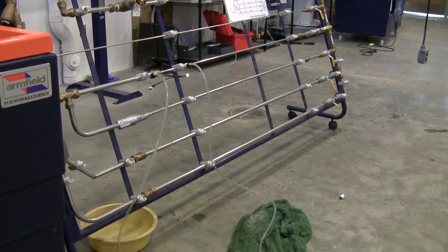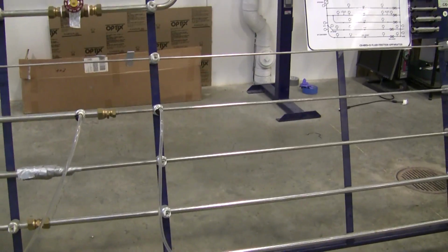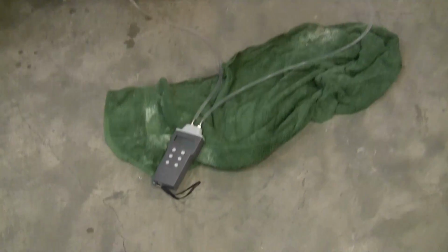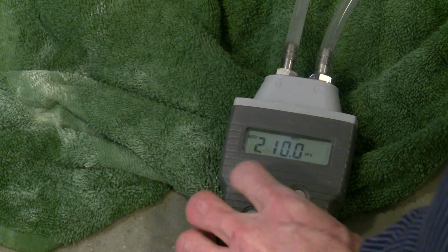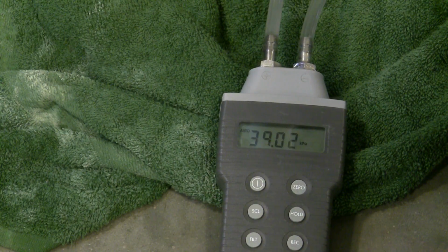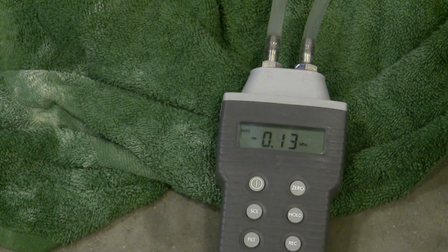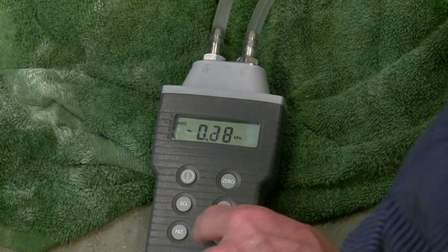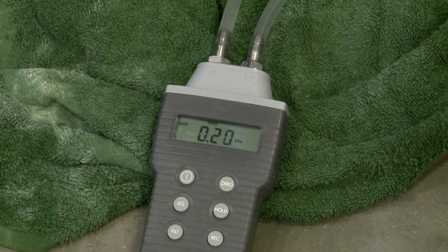Now we're going to measure the pressure difference through the sudden contraction. Turn the instrument on. I'm going to check the zero, closing the valve. If we do go down to zero, I'll just turn on filtering, re-zero it for maximum precision, open the valve, and now we're gathering data for the sudden contraction.